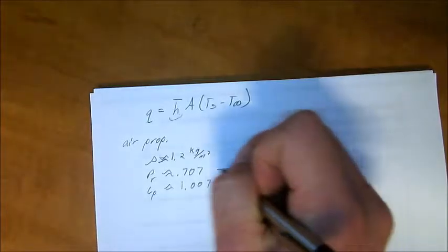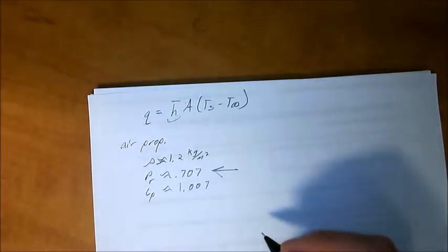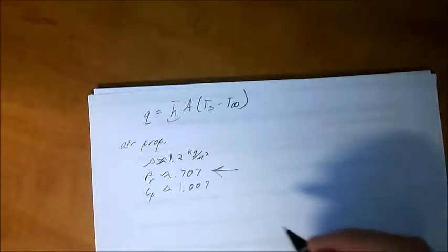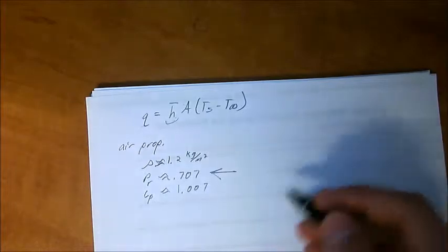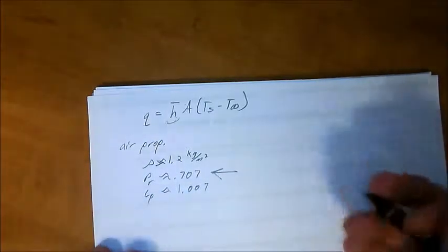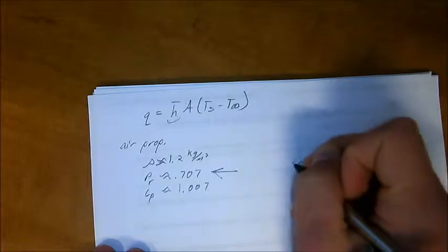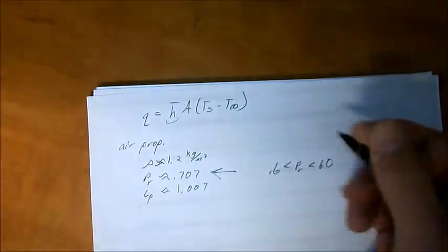So the Prandtl number right here defines which equation you're able to use. There's multiple equations that use Prandtl number, but the one for this case is defined by which Prandtl number you have. And the ranges depend on if it's greater than 1, if it's much greater than 1, and if it's between a range. But right here we have a Prandtl number that is greater than 0.6, which is one of the conditions.